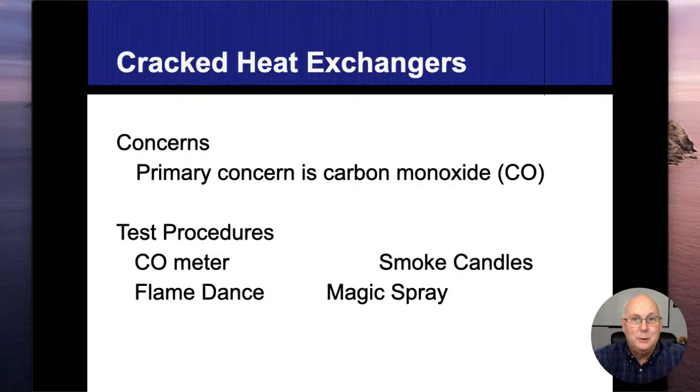The magic spray is kind of a joke a little bit, but it is an actual spray. I'm going to show a picture of it because I can't think of the name of it beforehand. But it has a lot of alcohol in it, and it is very flammable. And I've seen it work where it actually showed a hole or a crack in the heat exchanger. So with this spray, with the furnace running and the burner going, you actually put the spray into the blower fan of the circulation air. And when you spray it in there, like I said, it's very alcohol based, so it dissipates quickly.